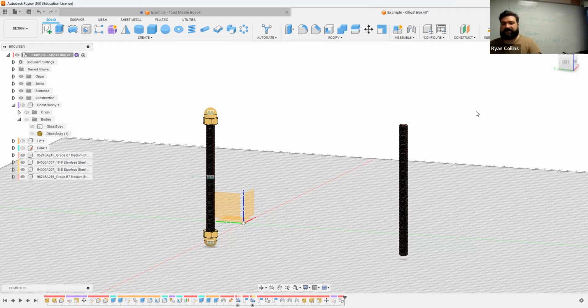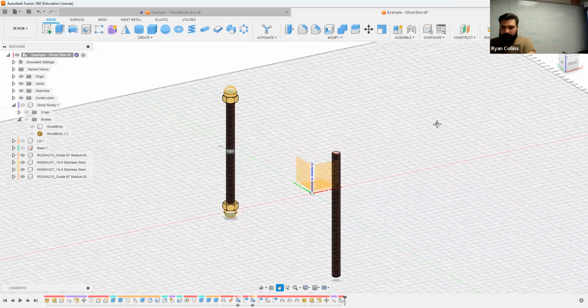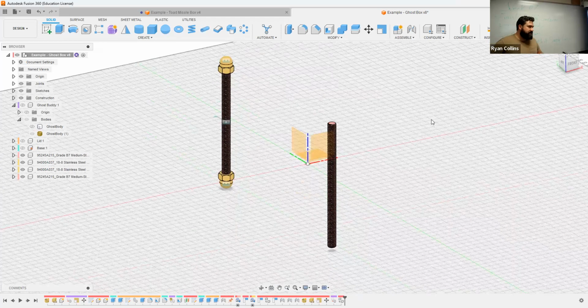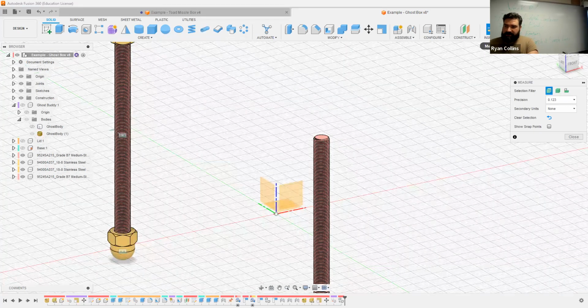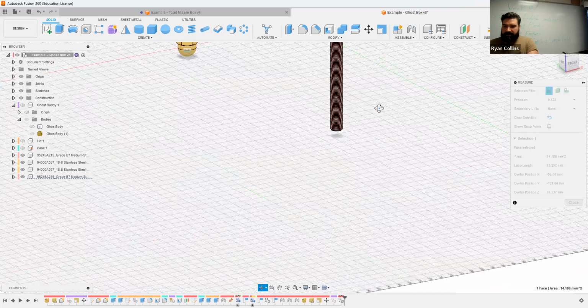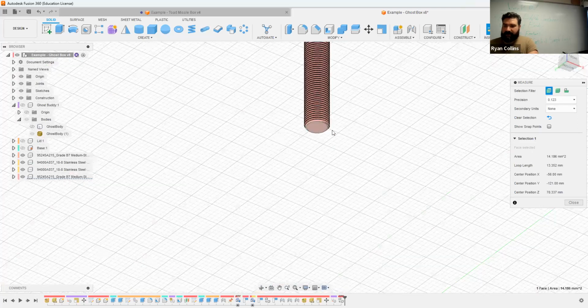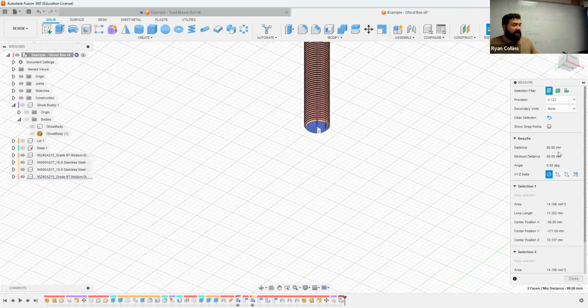The main thing I wanted to show you is how to chop this down. So yeah, you can measure this, you can use math, but why bother? We're going to make a measurement first. Just double check. All right. So measuring using the inspect tool, select the top plane there, orbit down, bottom plane there. All right. Now it tells me 80 millimeters.